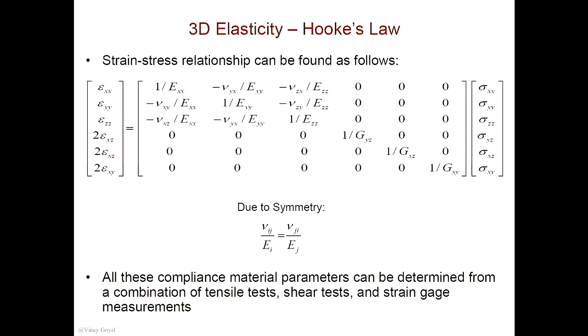For a composite material, which I already covered in lecture number 4, please review that again. You have several engineering constants that define the constitutive matrix, how the strain relates to the stresses. And we covered that these materials have directionality. For example, EXX and EYY are the in-plane directions of the composite.